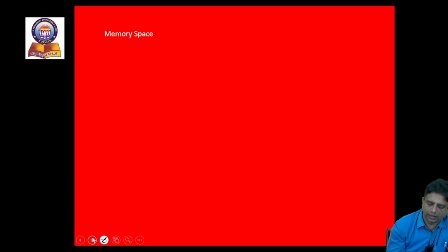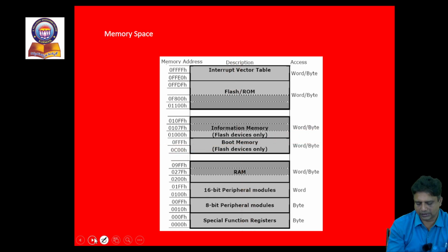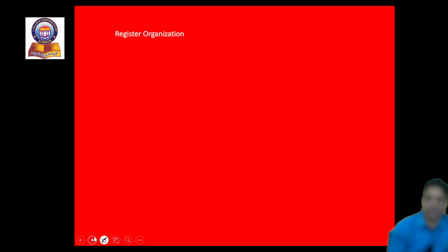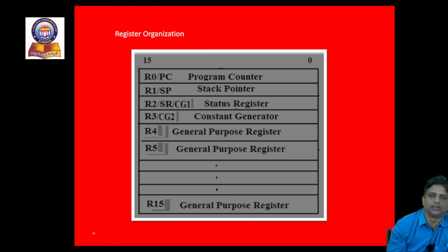Now, if we have a quick glance on the inner structures of memory, inner structure of MSP430 design, we could see the memory space 64 KB of allotted memory, out of which some space is allotted for peripheral interface registers and RAM, then a code memory called flash. In continuation, when we speak, there are some support registers with respect to MSP430 CPU operations. Most popular names, they go with heading called processor registers.